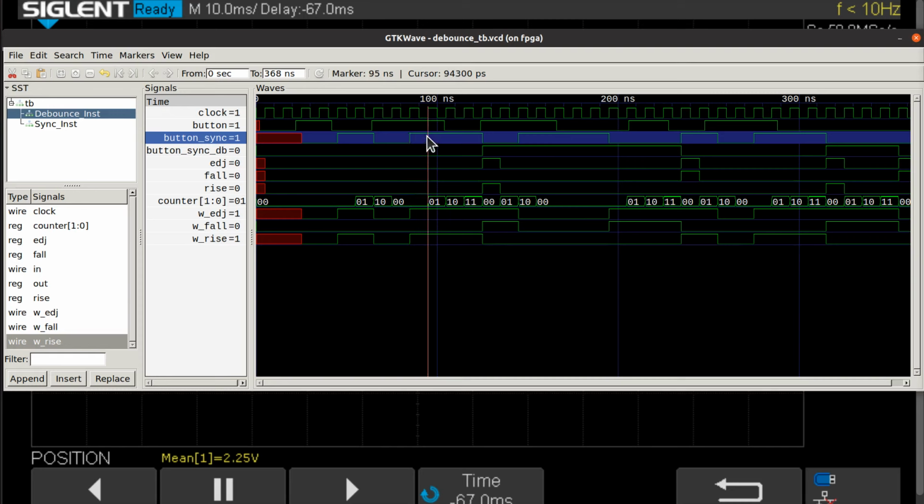This leading edge, we got a 1 on the input, a 0 on the output. They're different, and we're not at the max because it's currently 0, so we advance the counter to a 1. Same thing here. The input's a 1, the output's a 0. They're different and not at the max. We advance the counter, we go to 2. We got another 1 on there, and we're now advancing to 3. And the internal logic is now that that is the limit. It is max count minus 1.